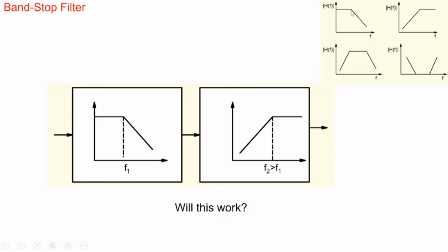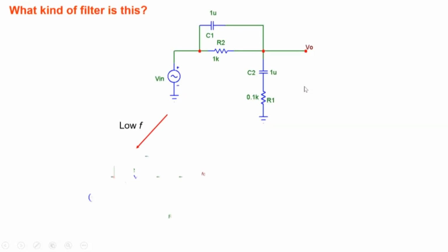But it's not easy. You can see that a simple RC circuit attenuates at a rate of 20 dB per decade. And if I build two RC circuits, maybe it does 40 dB per decade. Now, if you want 100 dB per decade attenuation, well, you will require many RC circuits, or you will require some other approach. That is here.